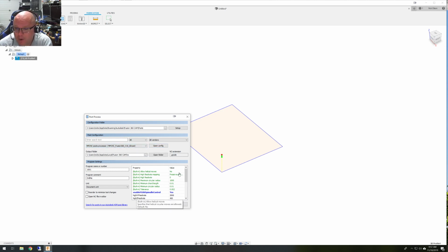If you look at the post processor properties down here, it has a macro for laser on, laser off. And so this is where I put my M107, and I use the fan 2 output on the Rambo to turn things on and off. Some boards, if you only have one fan, it's called fan 0. And just typing in M107 and M106 is good enough because it defaults to the first output. I need it to be P2 in this, so I get fan 2.